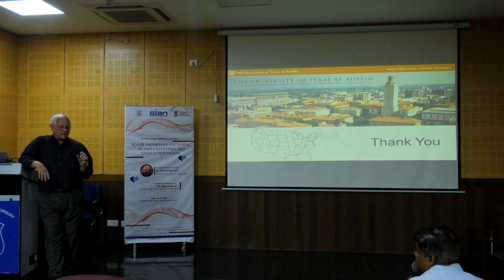What we do, as the starting point, is we take typically a 1 centimeter cube structure, and we lay out in the powder bed an array of maybe 25 or 30 little cubes, centimeter size. Then we keep all the parameters constant except the power, which we can change on the fly.